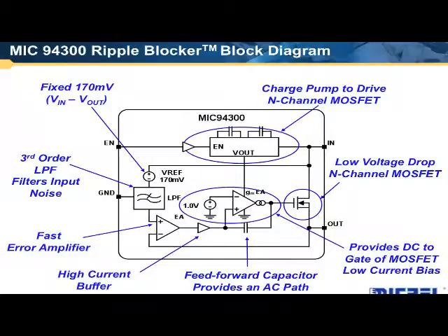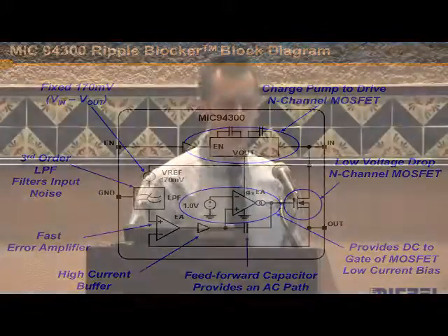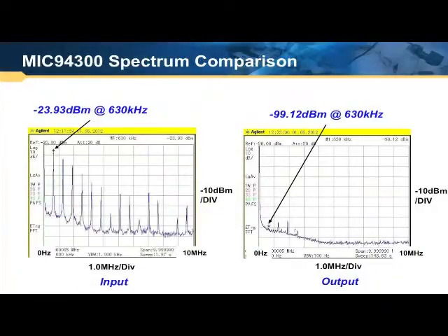We've chosen an NMOS output stage configured as a follower because of the natural suppression that gives us. This reference is set to hold that always just into the active region. And by doing that alone, we can get about 25 dBs of flat band suppression, just from the fact this is acting as a source follower. That suppression continues up in frequency until you get an output filter here.